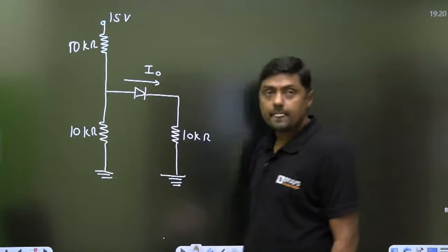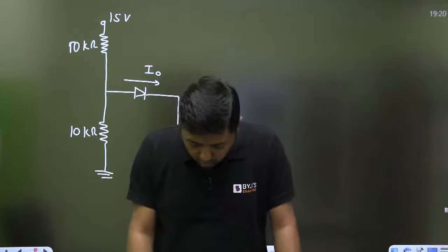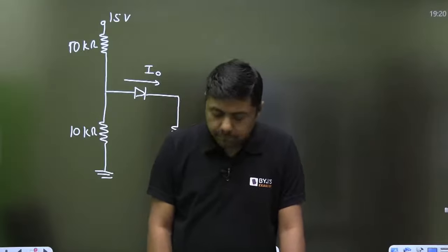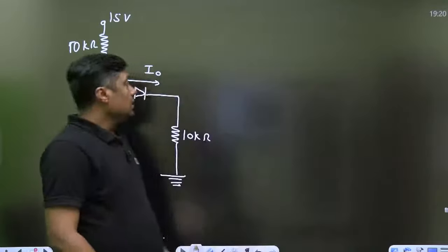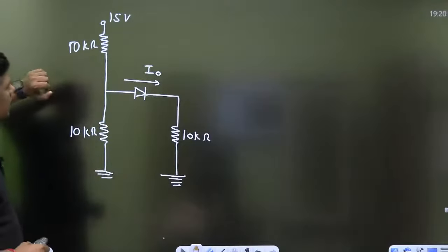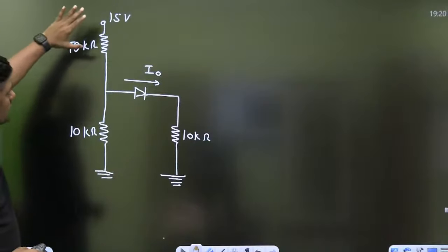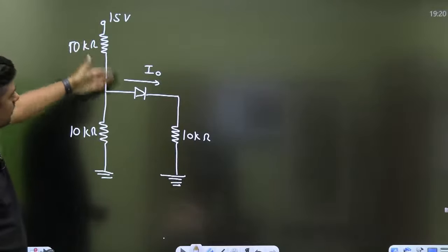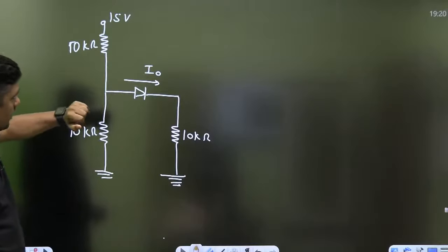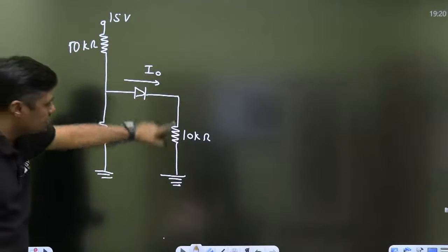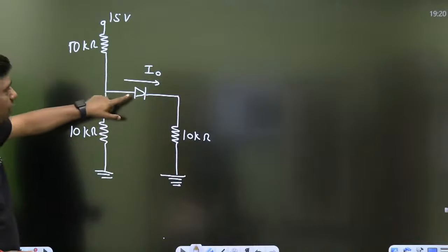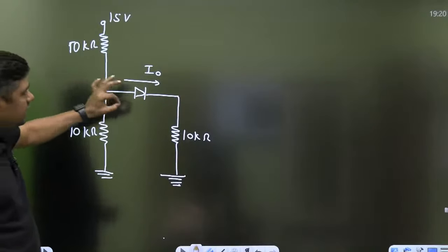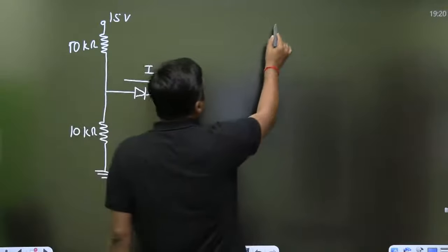Yes, Lucas. What is this? Forward bias or reverse bias? Everyone. So this is very simple. Under ideal condition, when 15 volt is connected here, it is towards the positive side. So normally we are thinking that this diode is what? Forward bias. Because of that 15 volt, there is no battery opposing, then that diode is forward bias. Under ideal condition, this diode will act as short circuit.